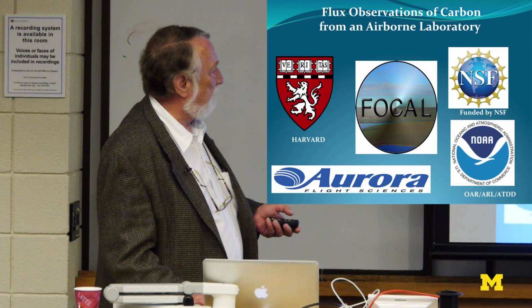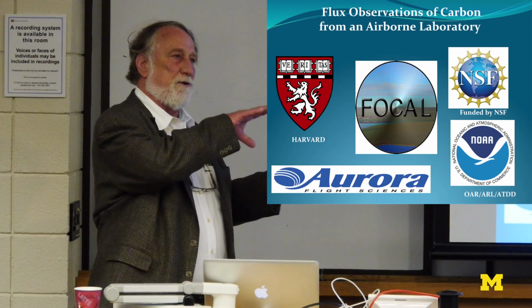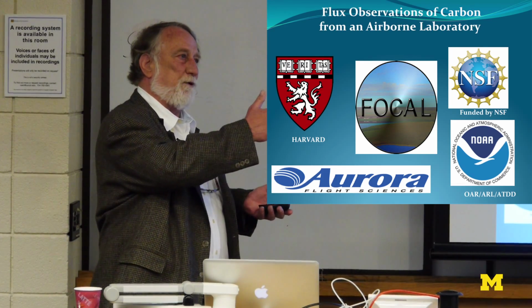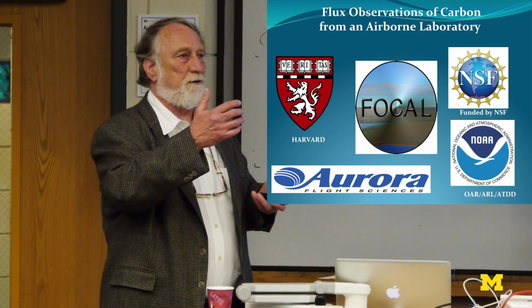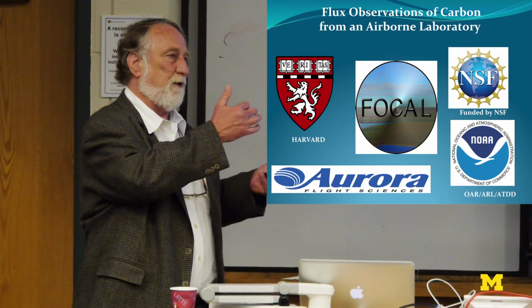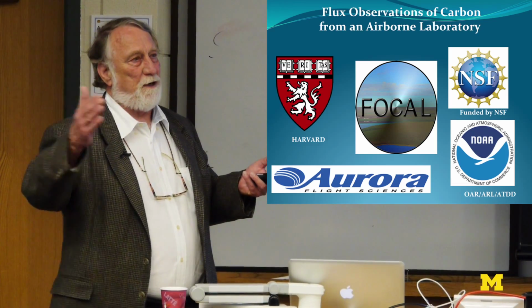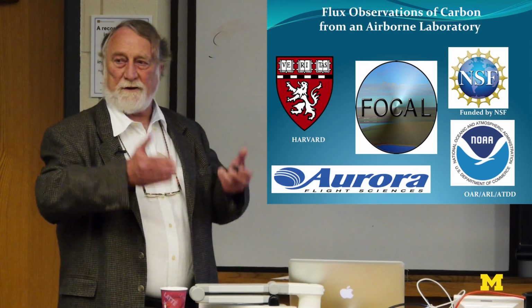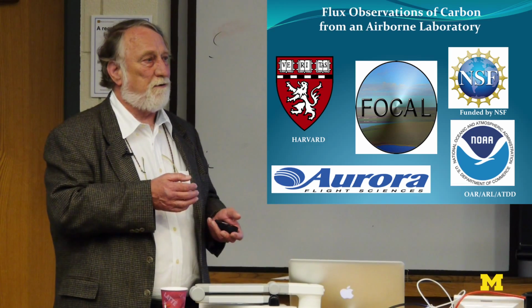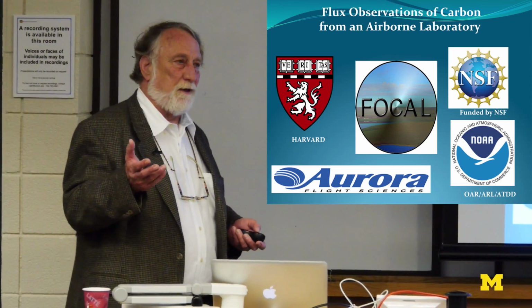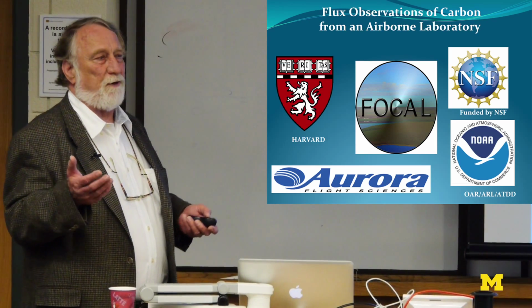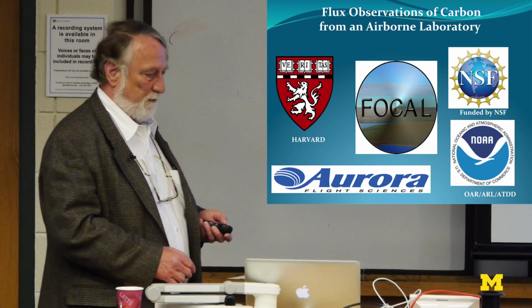And our lab has developed the instrument that goes on the nose of the plane. It's got pressure ports on it, and you look at the differential pressures, and from that you can get the UVW fluxes of the wind. So if you couple these UVW fluxes of the wind with these chemistry measurements on the backside, you can actually start looking at sources and sinks for methane and CO2 in the permafrost regions. And the whole concept here is what's the magnitude of the melting permafrost, what's it contributing to greenhouse gases?